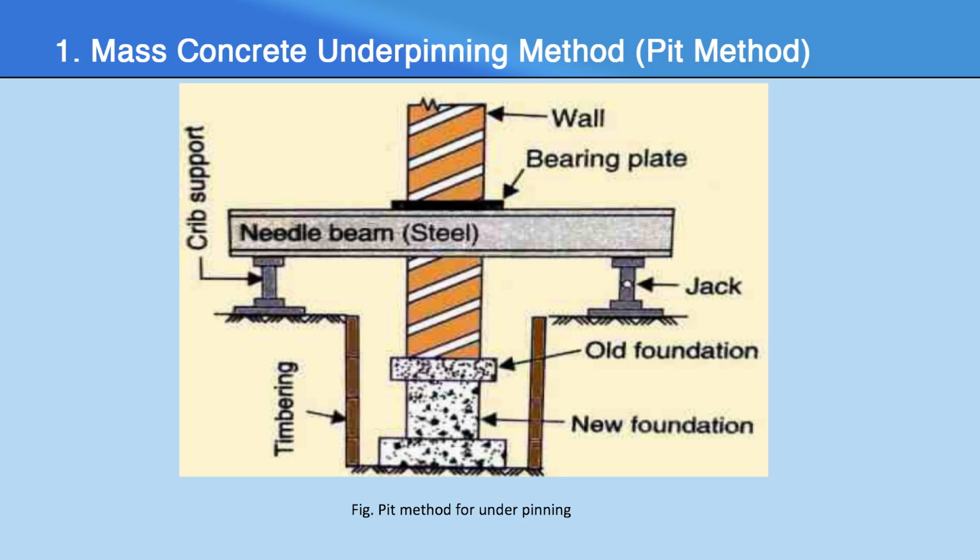This is the photograph of the pit method for underpinning. In that, first a needle beam is provided in the wall above the plinth level, and below that we construct a new foundation. Second method of underpinning, that is underpinning by the cantilever needle beam method.